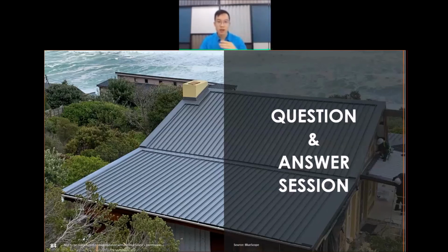We know that in South Africa the seawater is much saltier. So the salt accumulation on an unwashed area in South Africa would be much faster compared to here. I would not be able to tell you how fast you will see premature corrosion in a different environment, but different environments could show you the effect differently, depending on the timeline. Another factor that affects the premature corrosion timeline is the choice of material.